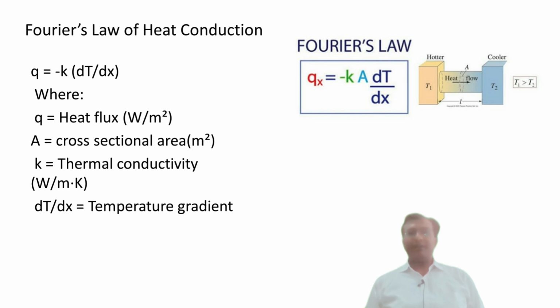Now we will look into Fourier's law. It is important in conduction analysis. Fourier's law states that the heat flux q is proportional to the temperature gradient dT/dx and the material's thermal conductivity K. Mathematically, it is expressed as q = -K dT/dx.